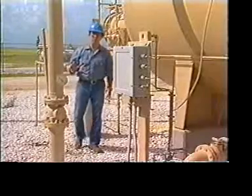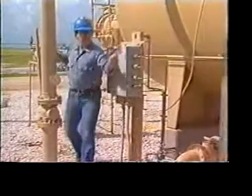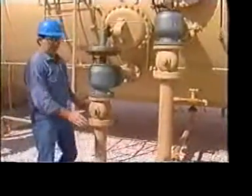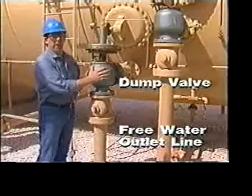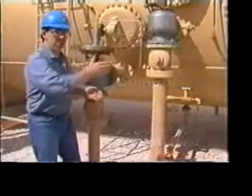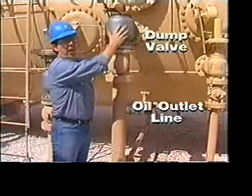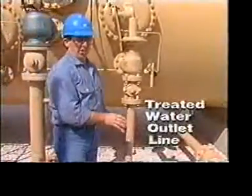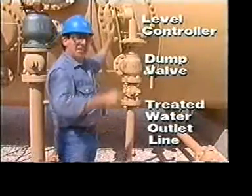As mentioned before, the produced fluid enters the treater through the inlet line. Now over here, these are the various outlet lines for the treater. This is the free water outlet line with the free water dump valve and the level controller. In the center is the oil outlet line and the oil dump valve. This is the treated water outlet with its dump valve and level controller.